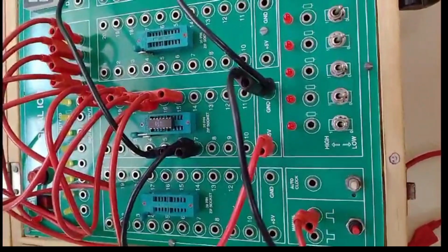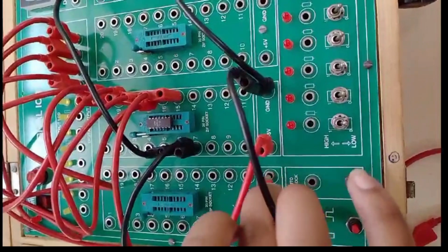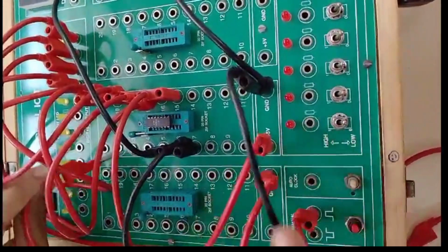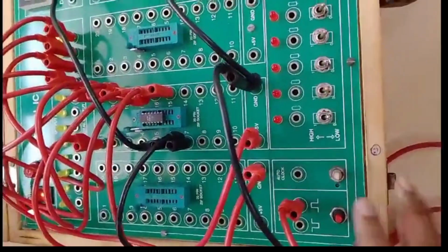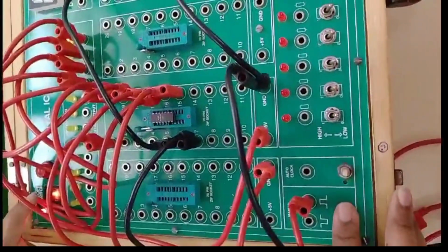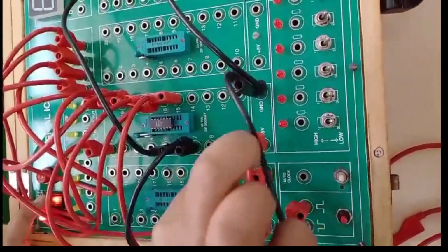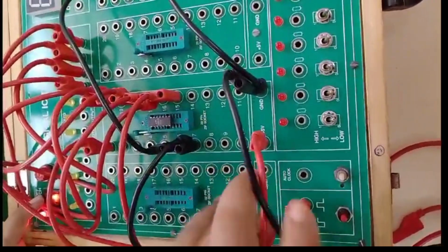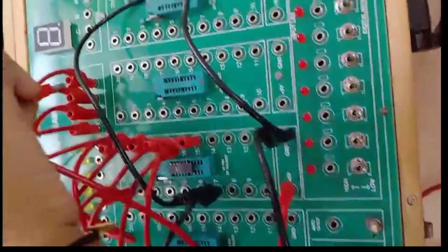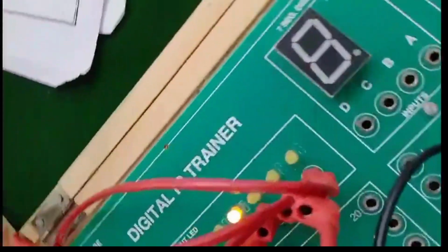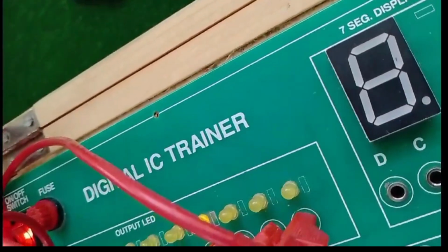Now connect one wire to pin number 1, and initially that wire is connected to ground. Now just apply a few clocks to clear all flip-flops. Now remove the ground and connect that wire to VCC. Just apply a single pulse, due to which QA becomes 1. Now just observe the operation of QA, QB, QC, QD in the ring counter.